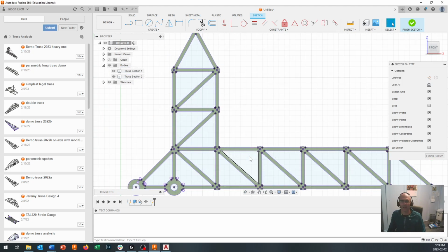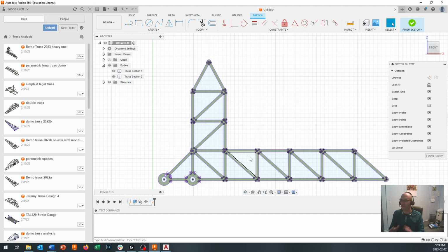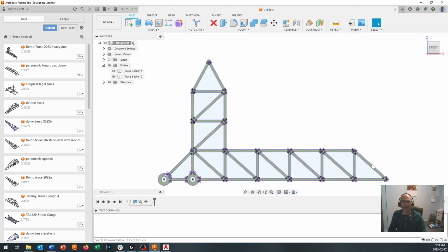Then I can click OK. And that's all you have to do to create the sketch. We just needed to go out there and find the things that were already existing and say, okay, just project them onto this sketch plane. And I know it doesn't look any different aside from these little dots here, but those dots are useful. I'm just going to click Finish Sketch now. And we now have a new sketch that exists right here.